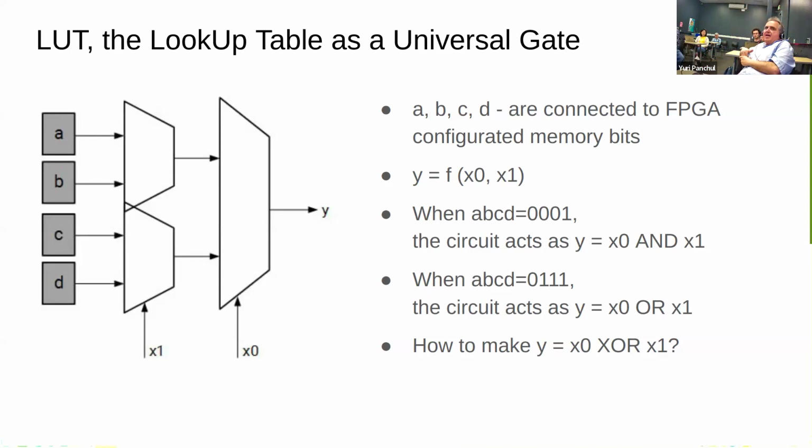A chip in an end device runs at a frequency of, let's say, 1.5 gigahertz. With such an FPGA box, it will run at about 10 megahertz, so it will run 2 orders of magnitude slower.